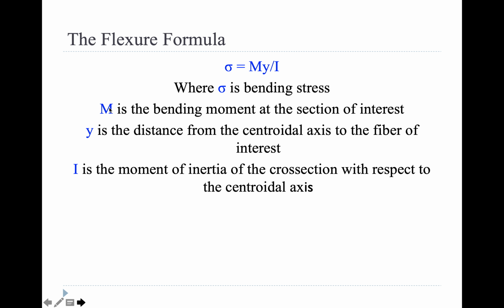And this is determined from the shear and moment diagram. So unfortunately, if you didn't like that topic, you might still need to brush up on it because this is where this comes from. Sometimes it may be given to you, sometimes it's not. And it's also to be noted here that this is always the maximum absolute value. So you always choose the biggest number from the shear and moment diagram, particularly from the moment side, even if it's on the negative side.